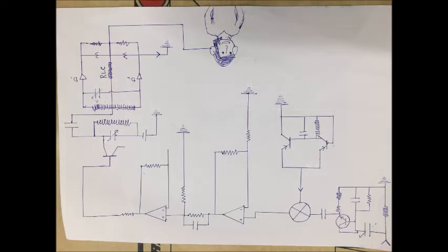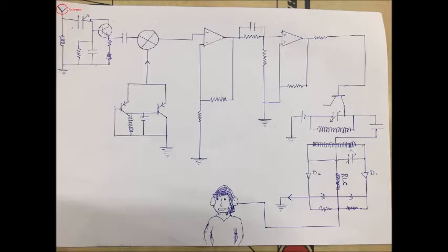So this is the detailed and quite possibly the simplest circuit for an FM radio receiver. So first comes the antenna, which converts all the EM signals in its niche to alternating currents, which is friendly to the circuit. Right, so coming to the RF amplifier, the basic functions include amplifying the waves and acting as a coarse filter by providing a short bandwidth.